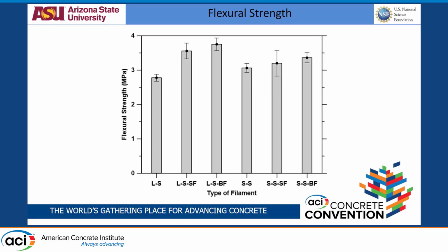When a steel fiber breaks, it most probably causes the fiber to completely lose its load capacity at that point, while basalt fibers prevented certain kinds of breakage. And we see that with basalt fibers we even got a slightly higher increase. Ductility is a question that comes into the picture, but as peak load capacity, as flexural strength, basalt fiber provided higher strength. Another significant thing we see is doing a linear versus S for a non-fiber system. S did help you gain more strength.